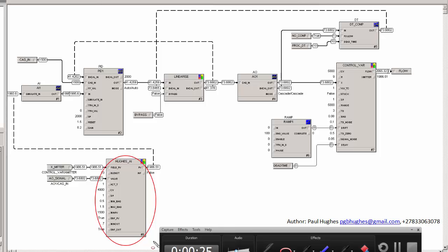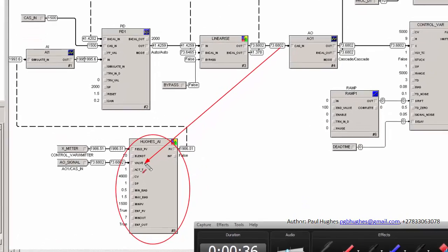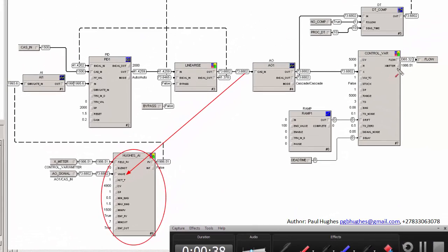the block to initialize. In theory, I could have taken this output connection here directly and sent it to that valve connection there, and I could have taken the transmitter PV and connected it to there, but there was no need to do that. If I use these internal references, which is fine, it achieves the same result. So in this particular example now, it is running,